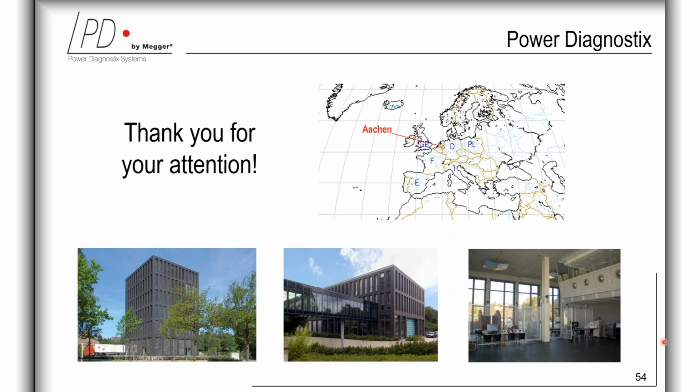So partial discharge measurement is one method to find defects in insulation materials, or to find weak areas in insulation materials. But there are also many other defects in electrical equipment that can be found by other methods, for instance, by dielectric measurements using the other Megger instruments available. The PD measurement technique has the advantage that it's a non-intrusive measurement method, and it gives an early pre-warning before it comes to a full breakdown of the insulation system.